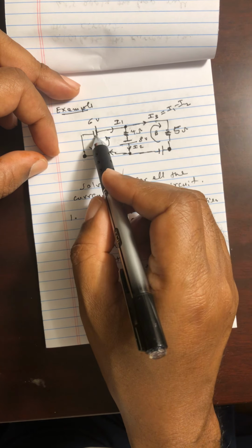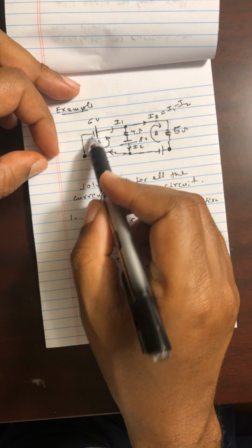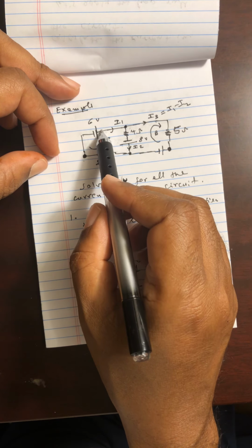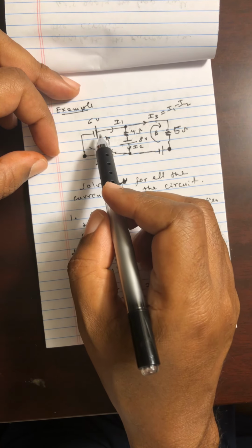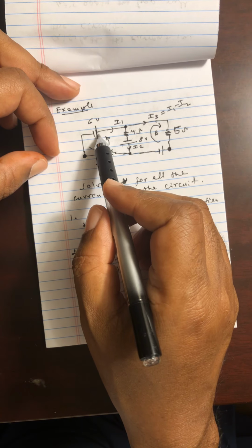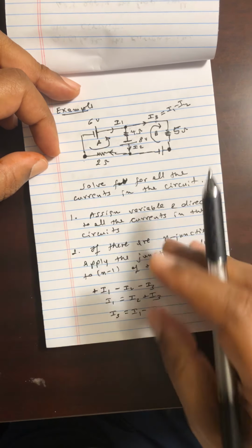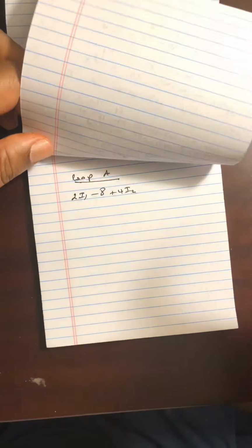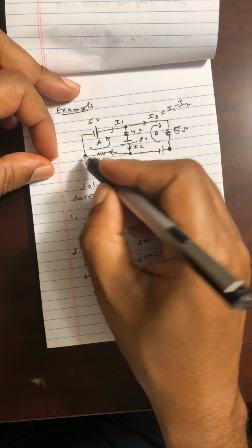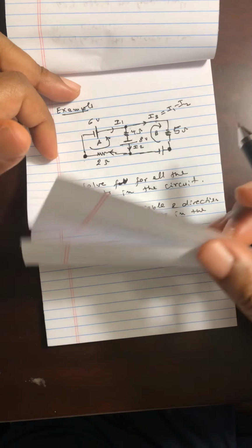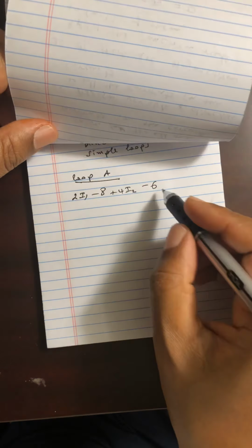all right? I keep going, I find this battery. I'm crossing this battery from the positive to the negative, so the potential difference is going to be taken to be negative according to our sign convention, because I'm crossing it from positive to the negative. So that's minus 6. I keep going, I'm back at where I started, and then I add all of them up to 0. Okay, so this is my first equation.